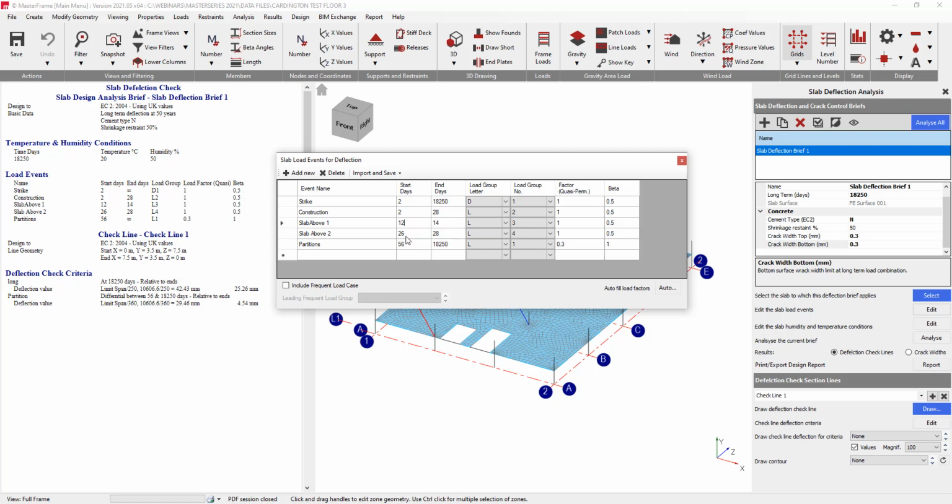We've then got subsequently another slab above that yet again, so we've got propping through 2 levels, and there are publications that talk about how you calculate that propping load through, and generally, obviously, as subsequent slabs get applied, so you might even have another slab above this yet again, those loads would generally decrease. But those were documented for this Cardington structure, and they've been applied in load groups L3 and L4 as finite element surface loads also. Final load then is a load applied at 56 days,